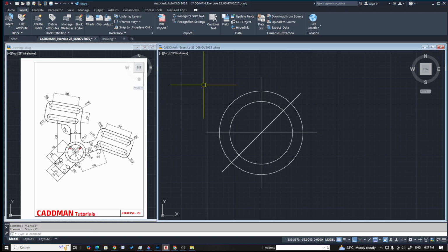So first try to offset to a distance of 15 on the other side in order to get our object end lines. So go for offset, say 15 from here to here, and from here to here, and just trim out the extra parts,